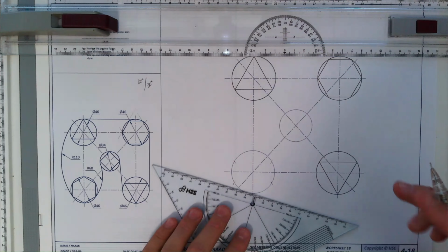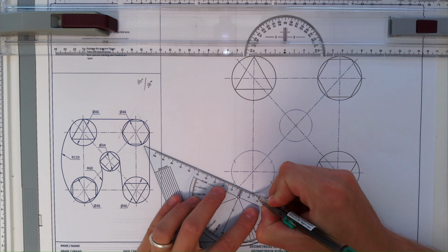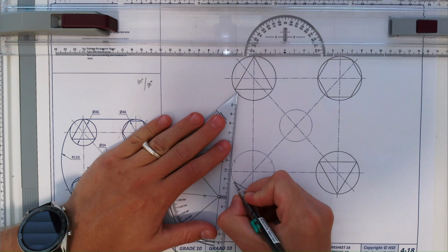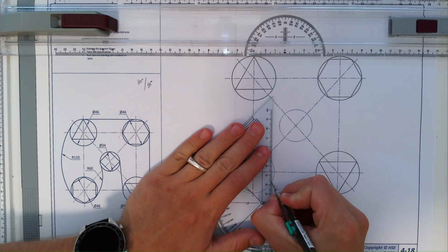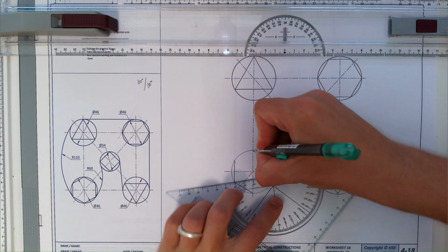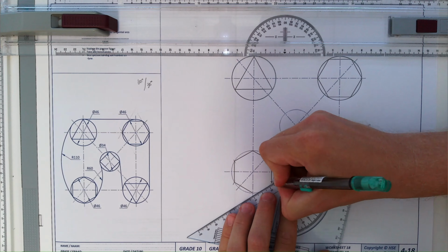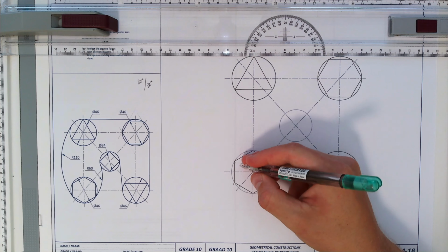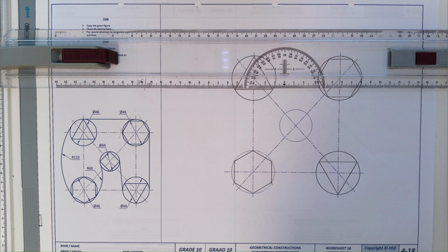And then what you can do is just use a ruler or a set square and connect from that point to the points you've made, from the one to the next. Connect as solid lines. When you make these marks, they should be light in construction so they don't interfere with your final product.